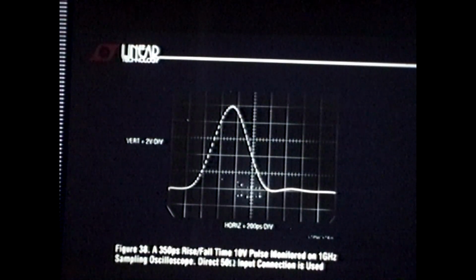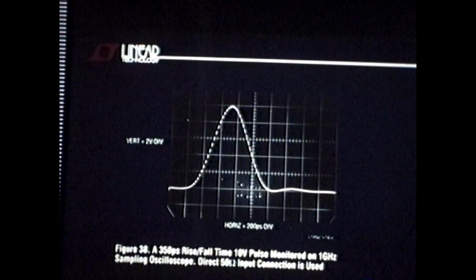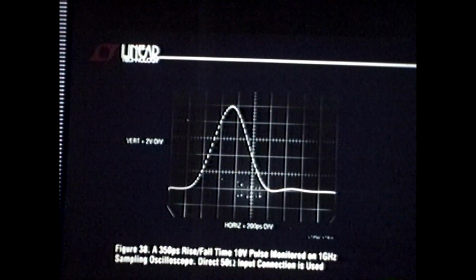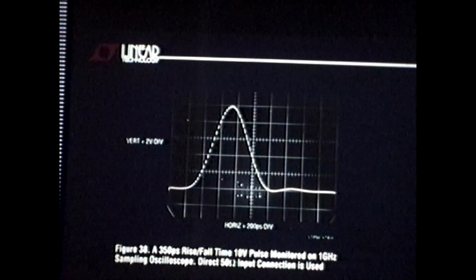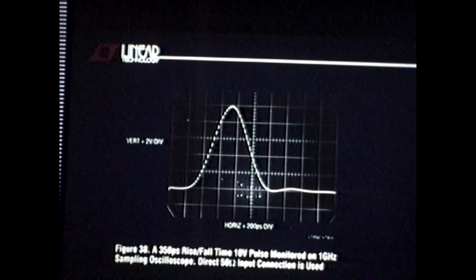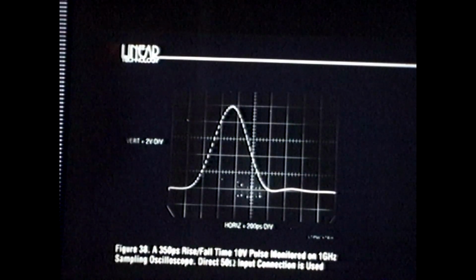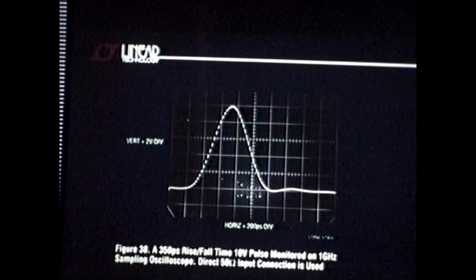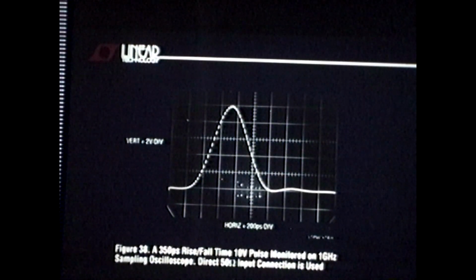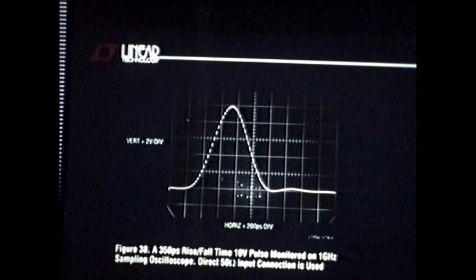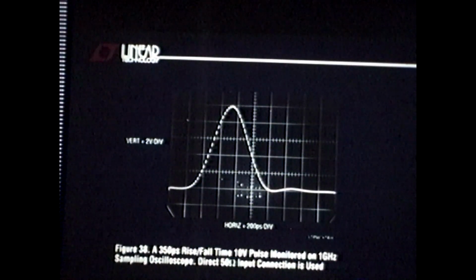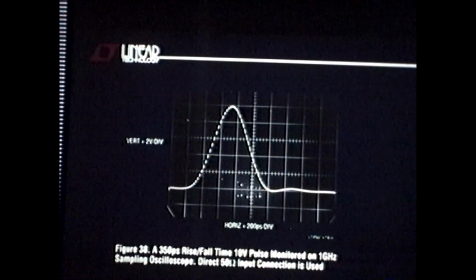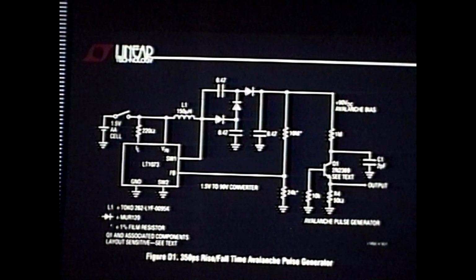Of course, I stole the basic technique. This is pretty much a stripped-down version of the technique that Tektronix used in the 60s to generate the gate pulses for sampling bridges. Because when you build a sampling scope, the name of the game is, just like with a strobe light, how narrow a window can you look through as you take your samples. So there was all this science and art that went into developing gate pulse generators to get that bridge on and off with incredibly narrow windows. And this is essentially a chopped down version of this. If you're interested, I've also got a version of this, which if the art gets done, you'll see 6 or 7 lectures down the road where I can trigger this.